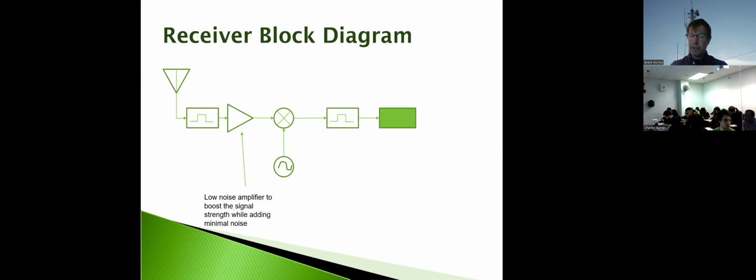So it enters a nonlinear region. And now in this case, superposition no longer applies, right? So your signals don't just add, they actually multiply. And so when you have two signals at different frequencies, they will mix and cause some additional interference terms.